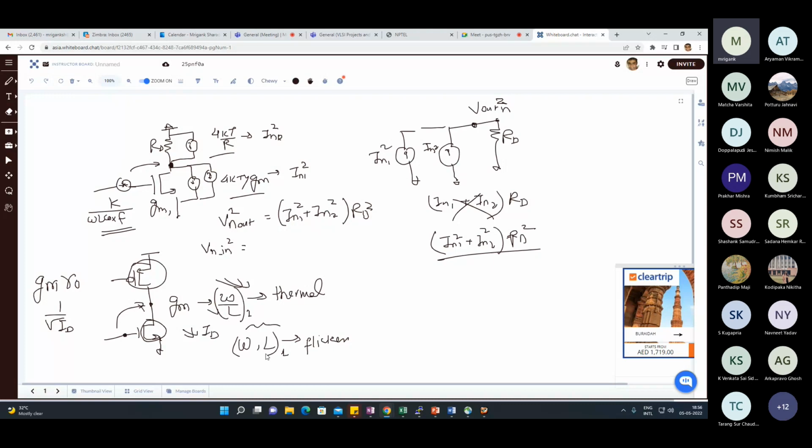So if you look at the input signal, in that case the gain is dependent upon RD. On one side you are having the RD, which is contributing to the overall noise in terms of root R, right? If you're looking at the current or the voltage, the noise is 4kT/R, whereas the signal is directly proportional to R, so that way you can say the signal to noise ratio will improve. So the spectral density Vn square is 4kT/R. The input signal gets amplified directly proportional to R. So if you look at the ratio, that will improve. That's the idea.